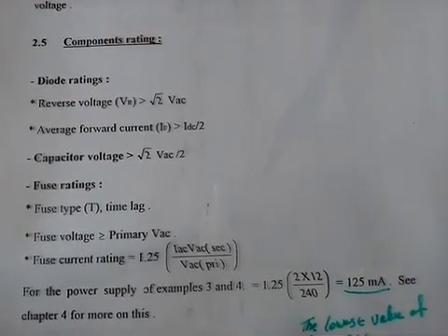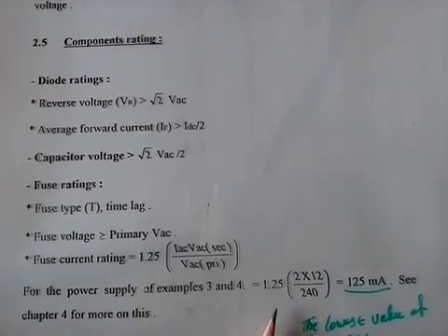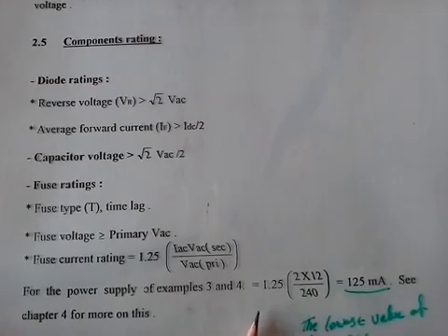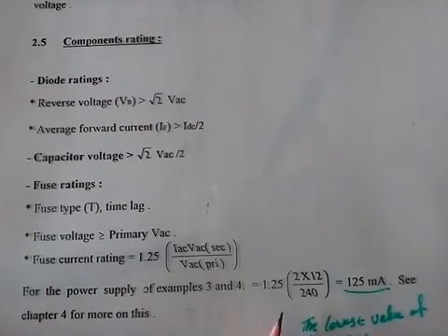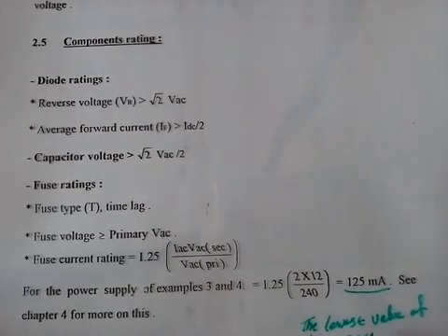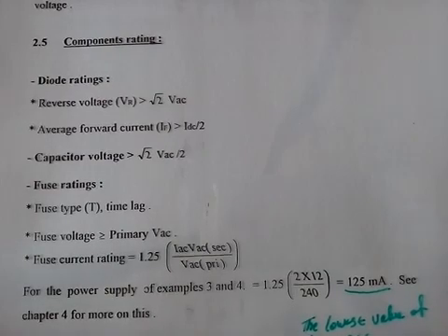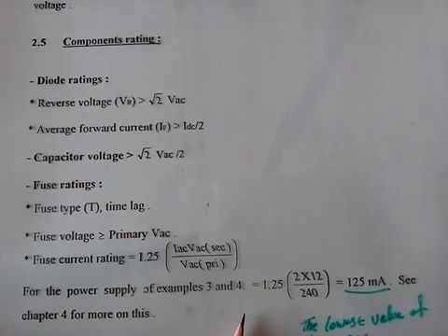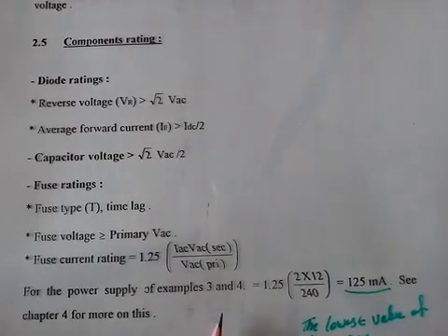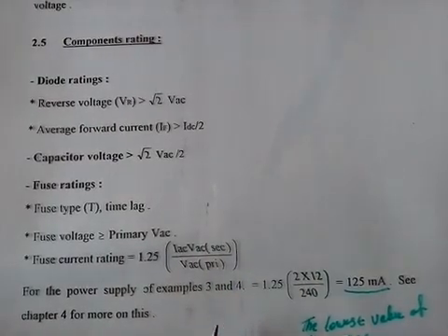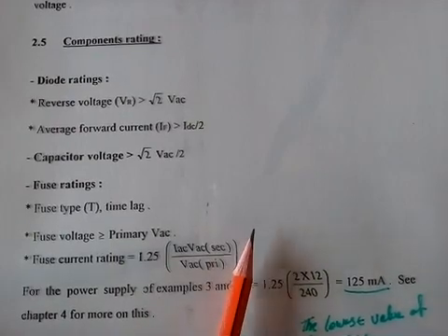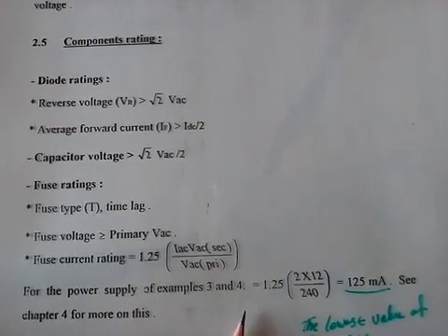Yeah, this deserves discussion. We're going to include that in another lecture on how such fuses are selected for power supplies. This is the lowest value of all types. The fuse value is the lowest of all types of power supplies. Why? Because the transformer is fully relaxed. It has 2 secondary windings, A and B, like we discussed before. One is active and the other is relaxed, and after that the other one is active and the first one is relaxed. So this relaxes the transformer.